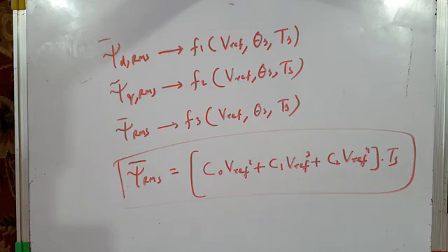And in the next lecture and subsequent lectures, we will see that when different PWM switching sequences are applied, how this stator flux ripple gets affected, and which switching sequence gives minimum stator flux ripple and hence minimum current ripple. We'll discuss more about it in subsequent lectures.